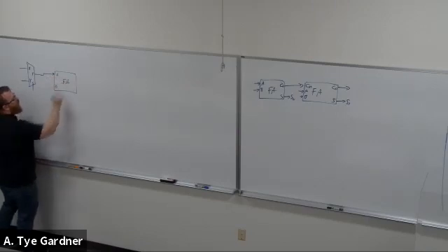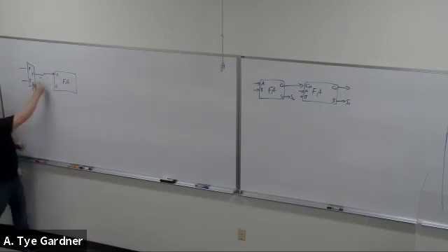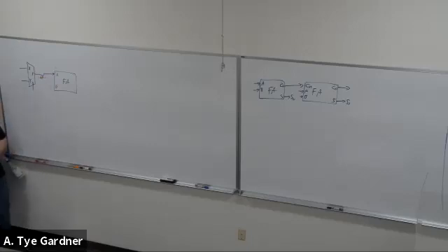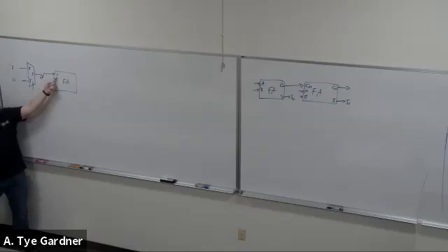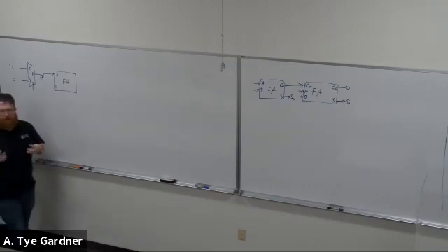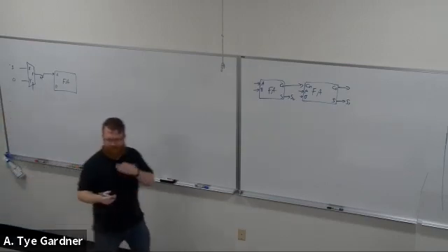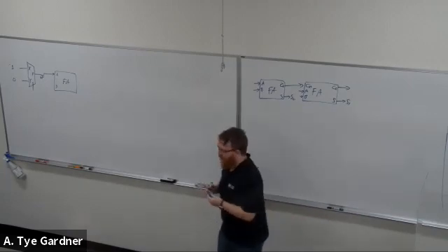this would be a full adder, right? I could connect up this input. We'll call the signal f, okay? So then if I put a value, 1 here and 0 here, if select is 0, it takes the 1 and puts it on the output. And so I would add 1 to whatever B is, right? So I get to choose my inputs. We get to build like a switching railroad, right? Tell it where the trains go. That's what we're going to build.